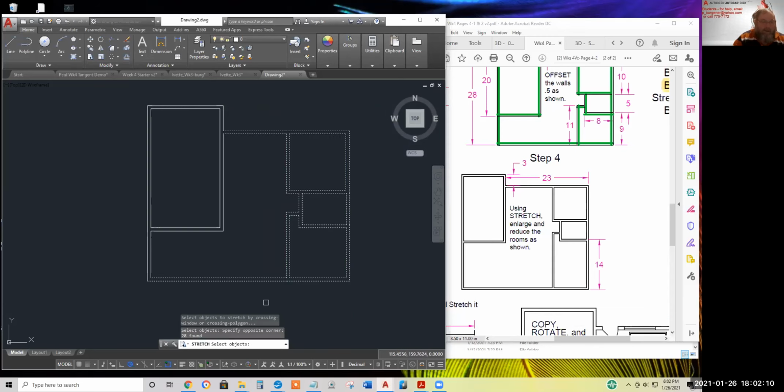Click. Now you can hold the shift button and deselect stuff if you want to, remove it from the process, but I don't know that happens often. And if you accidentally remove stuff with a crossing window, AutoCAD thinks that crossing window is what you want to stretch with.